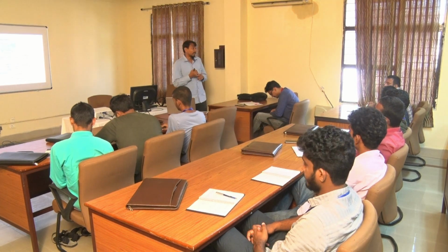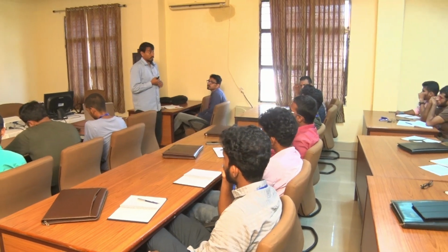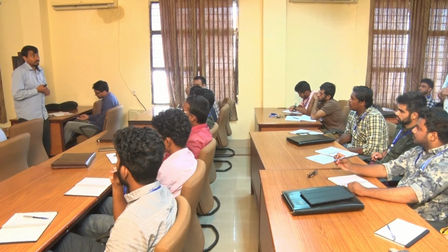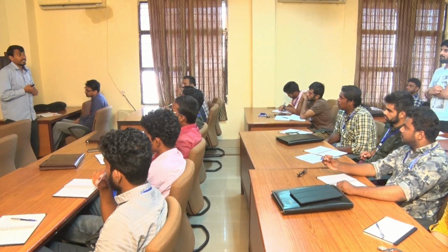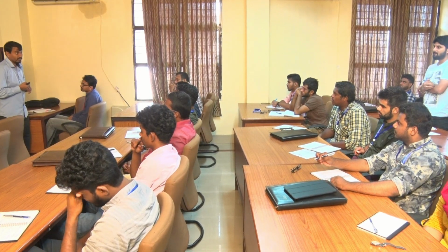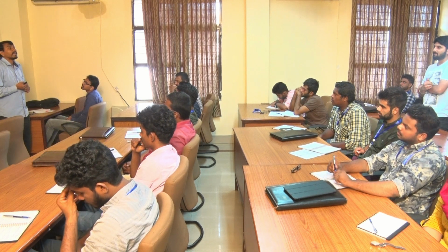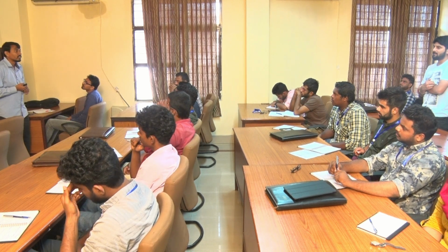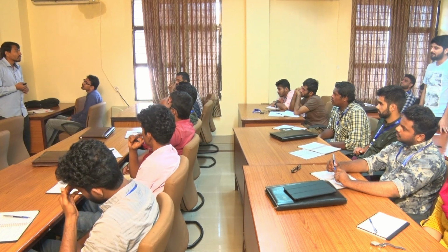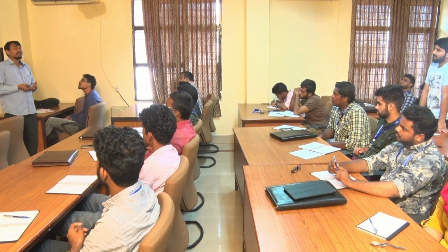One of the major corrections is for the rock slope. Suppose the joint is not favorable for you and you have come out with the RMR, suppose 76. If the joint is very unfavorable, then your rating would be 76 minus 60, that is only 16. So 16 RMR is a very poor category of rocks. So this approach actually came up later.